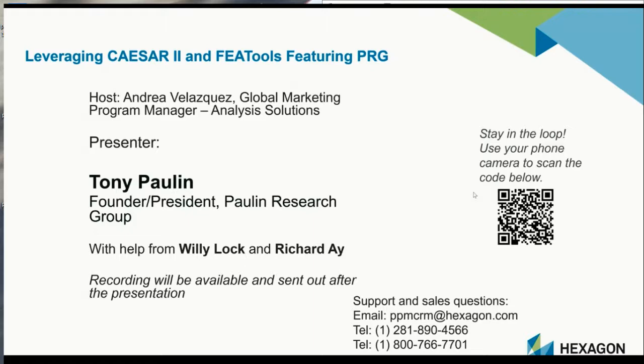Well, the allowable loads for the pipe shoes are obtained from finite element analysis, and what the wizard does is compare the restraint loads against the allowables from NozzlePro. I hope I answered that. And I think the concern is, what is the stress allowable in the pipe?